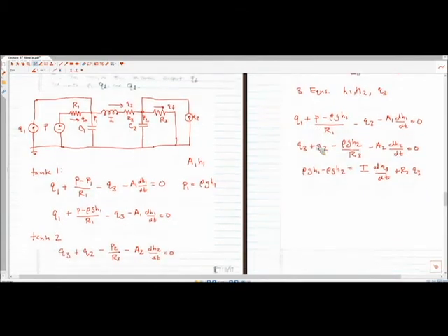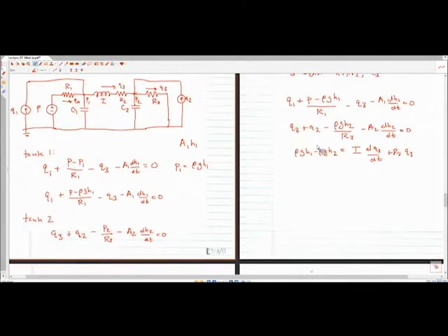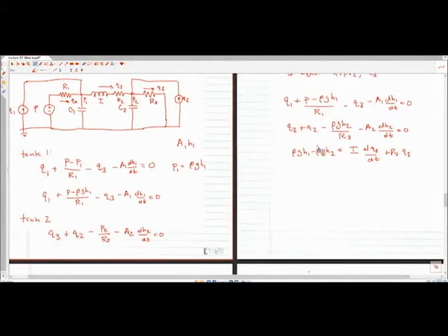So I think we only have 3 minutes left, so we're not going to be able to go through this complete problem. But I'll talk a little bit about strategy, in terms of this looks a lot like some of the problems that we looked at for the motors, the motor circuits. So the first thing in terms of strategy is the question asks for a transfer function, right? So as for a transfer function, we're looking at the Laplace transform. So in terms of steps to solve this, first step, let's take the Laplace transform. Second one is going to be then solve for, and the variable that we're interested in here is important. What the problem is asking is it wants you to find the flow rate out of the system in terms of this QF.